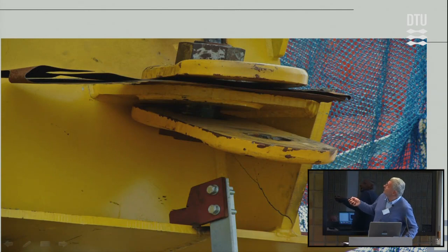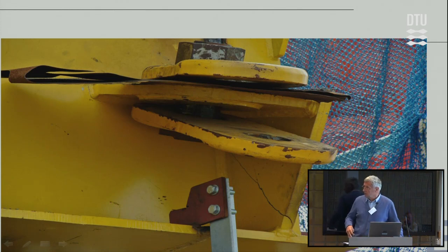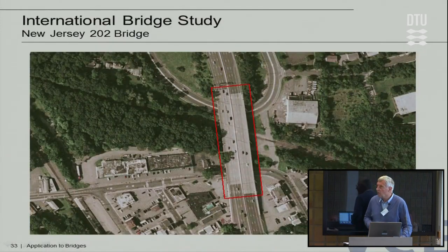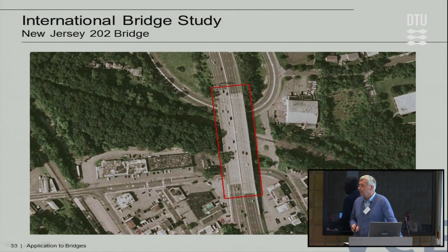You can see the damage here. These huge elements, this crack on a 35 millimeter steel plate, and the anchor here was completely pulled out by a resonance in the wake of this wind. The monitoring system could not have avoided it at all.